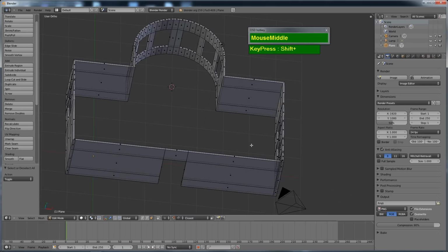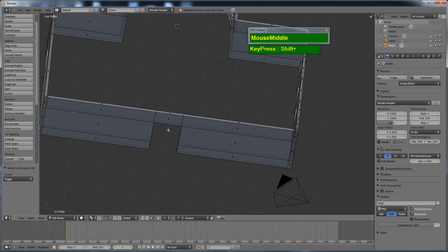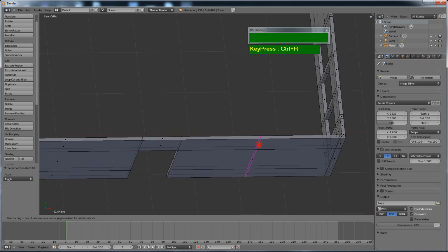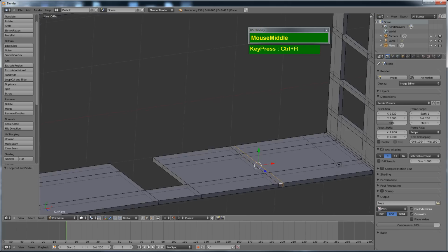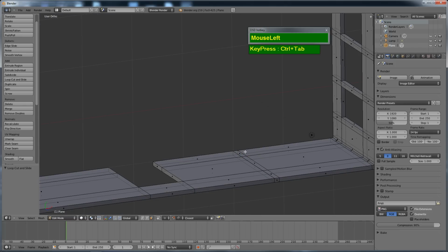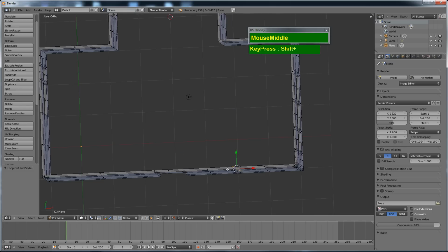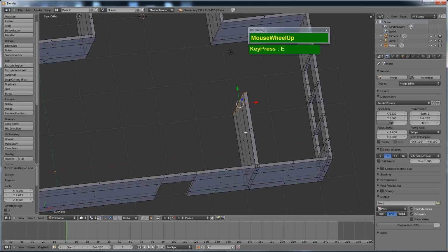Alright, so if you want to create the walls, because we already satisfy these parallel edges here, you can simply insert one edge loop, and then insert another edge loop, and then position it nicely. Now if you have a reference drawing at the base, you can use it as a reference.